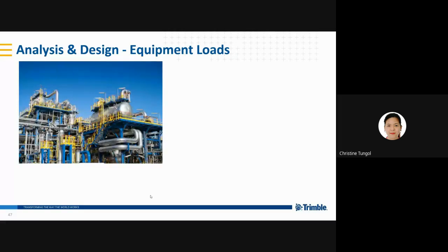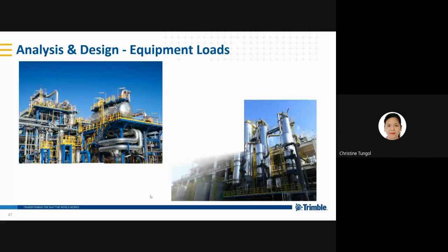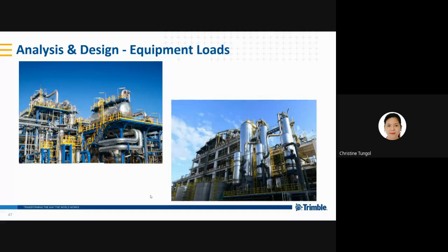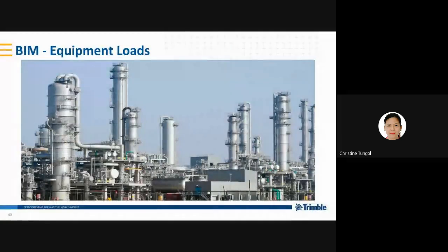So loads associated with or applied to equipment objects are decomposed and applied at the support points. The equipment object itself does not form any part of the analysis model. Only its loads take part in the analysis. It is accounted for in the design through the loads in the various equipment load cases. So in this phase, there is no beam associated with equipment objects. So let's see, it may come in future development. Nothing is impossible with Tekla.